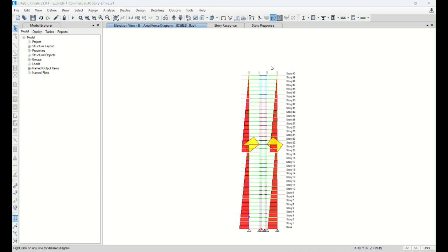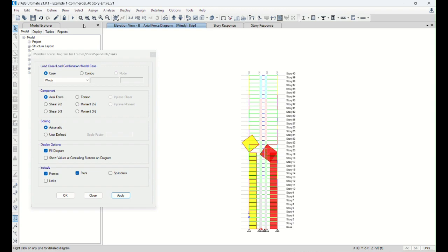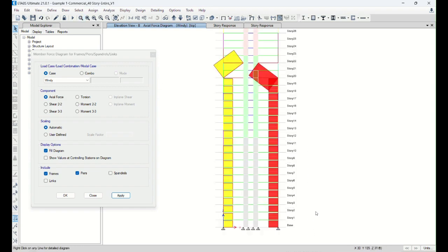So let's check how about under the wind load. Now we have a wind X Y, right? This is ultimate wind load. So see how this building behaves because of the lateral wind load, with the wind blowing in this direction, so this outrigger truss is working like a deep beam, interacting with the wall, so that on the windward side the column is experiencing tension, uplift, but the opposite side is experiencing compression, right?